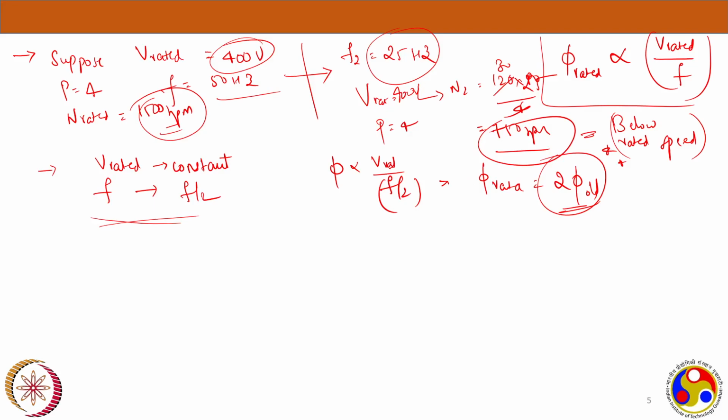Now whether it is a motor or a transformer, after it has been designed, you will have to look at its BH curve. It is a very important curve to understand the flux requirement of the machine. So what is the rated flux and what is the current requirement at that particular flux? Let me draw a sample BH curve.